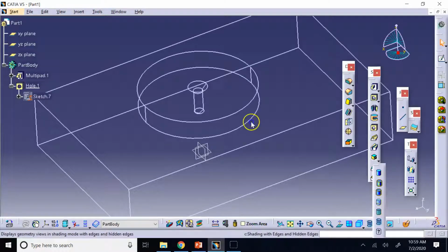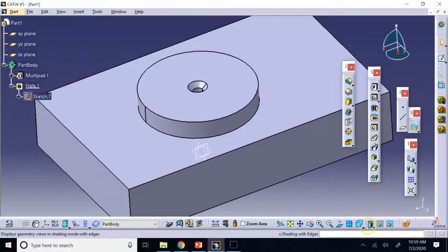So you might say, well, if I want to cut out a hole in an object, can't I do it with the cut extrude? All I need is to draw a circle and cut it down. Sure, you can. And actually, cut extrude has more power over hole, because not only you can cut out a cylindrical volume out of the part, you can cut any other shape, right? So the cross section can be trapezoid, can be hexagon, can be any shape. So pocket is more flexible, of course. You can do any shape and then cut it out.